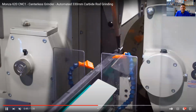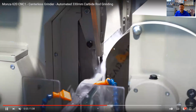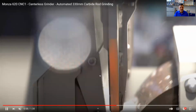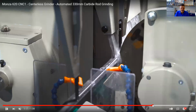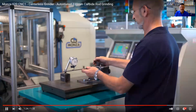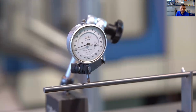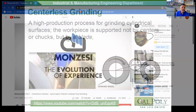So notice it basically can grind the entire outside edge in one shot because you don't have to hold on to the outside diameter. Centerless, you don't have to hold it by the center. So it grinds that entire rod and not much to see. It brings it out afterwards. And then we're going to check the run out tolerance on this rod. Remember that? We've done run out before, right? It's a dial indicator checking it. But look at the run out. Barely any run out on the end of that 330 millimeter rod, thanks to centerless grinding. So that would be centerless grinding.